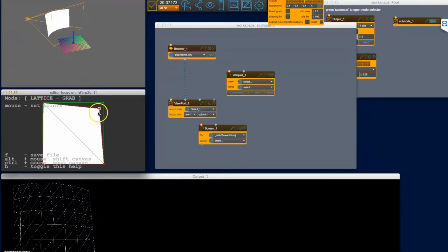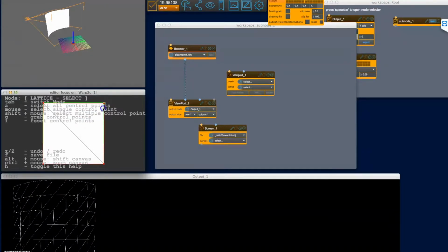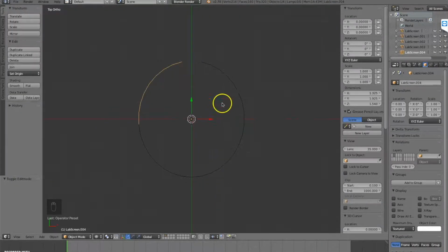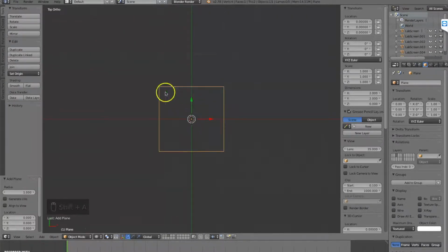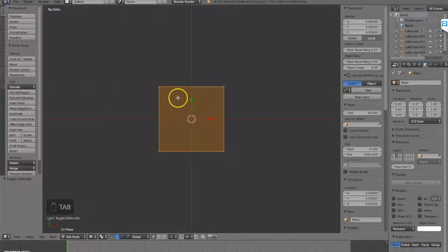However, for this purpose, the mesh does not have the right resolution, so we have to create our own mesh. And for this we quickly step over to Blender. I'm going into a different layer, press Shift A, create the mesh plane, tab into it and subdivide it.